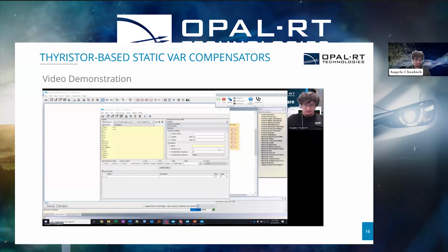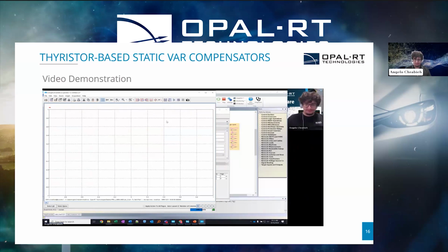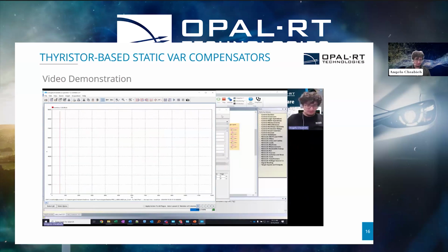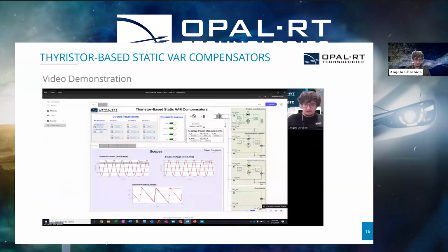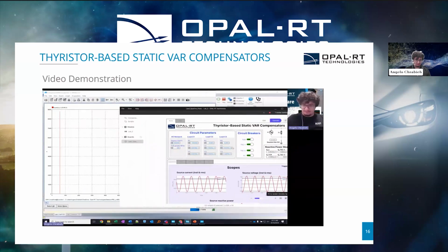Let's go for the source current on the output of the transformer, and the first 11 harmonics, let's say, add function, run. Okay, so here I have already the filters activated. Let's deactivate them. So I'm gonna deactivate the filters, run.